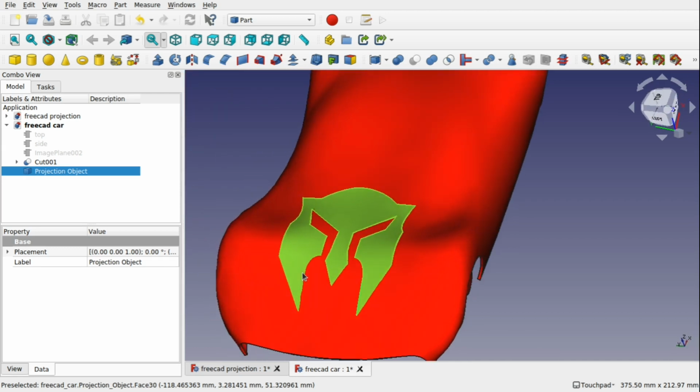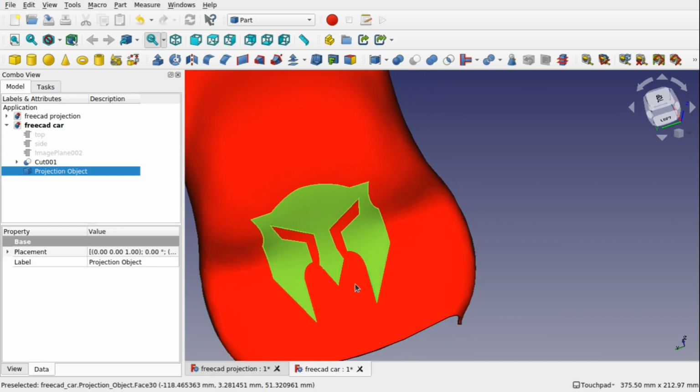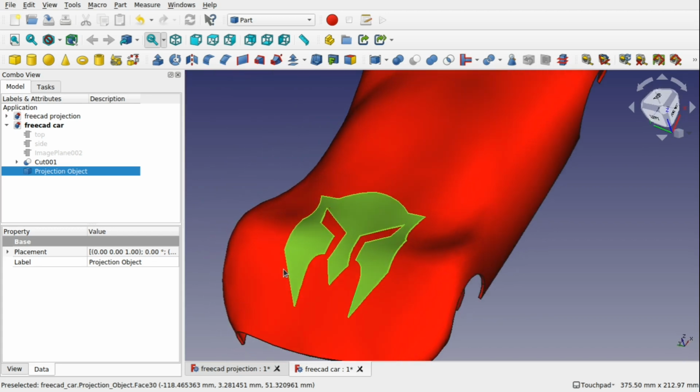So this is a video in regards to a few comments I've had on my channel. I think there's been about 3 people that asked me how to create geometry or faces on curved surfaces from sketches or wires, and this video will show you how to use 3 different tools to create basically the same effect. So you can use one tool that's in the part workbench, and there's a couple of tools in the curves workbench as well.